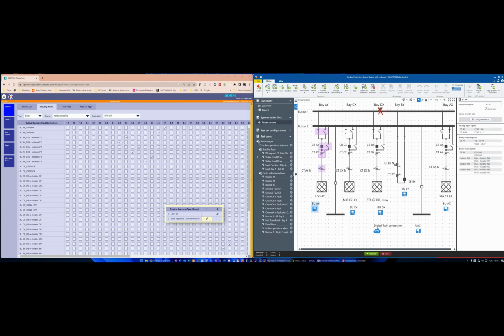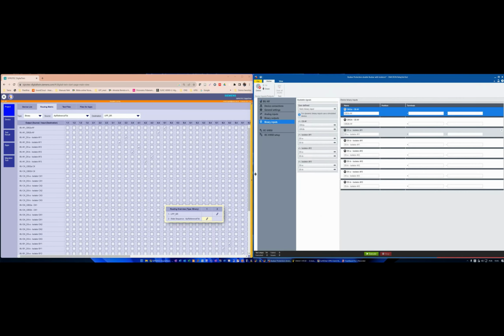You come here in the bay unit, and we can see, for example, my binary input, and in this case is the isolator. And I connect this connector, this contact here. So in my bus bar configurator, you can see the name of the binary input in my relay, because here is my source, that is the IP reference, that is this one, and here is my destination. So all the equipment is integrated with my relay protection, okay?